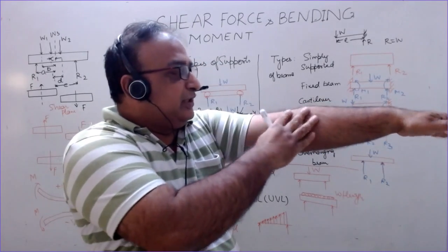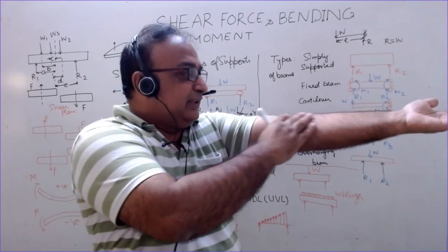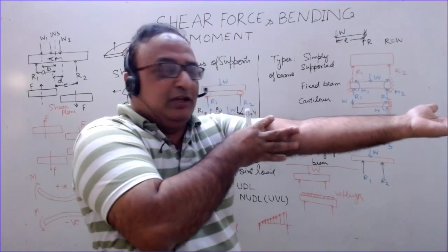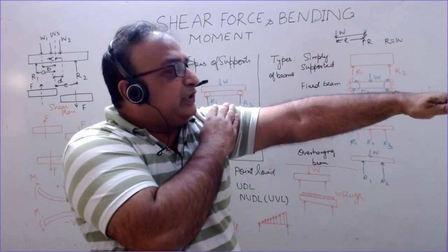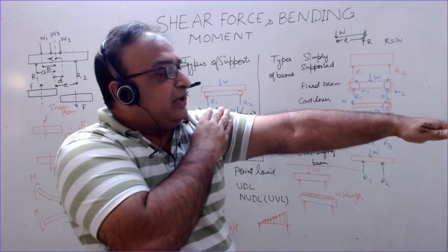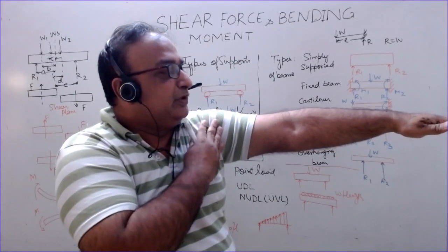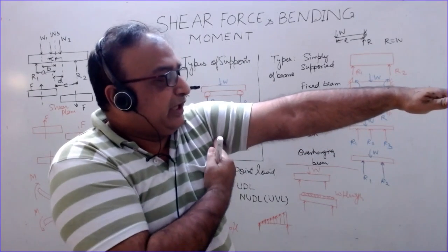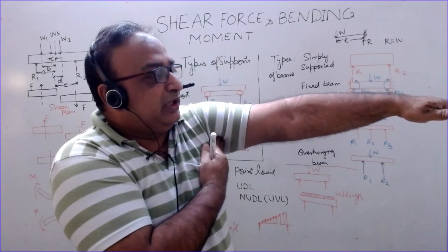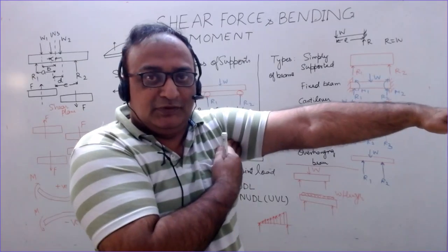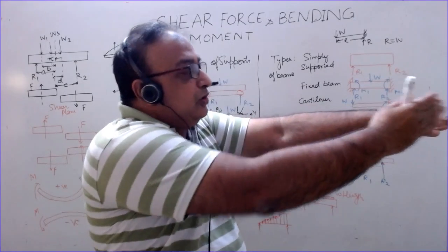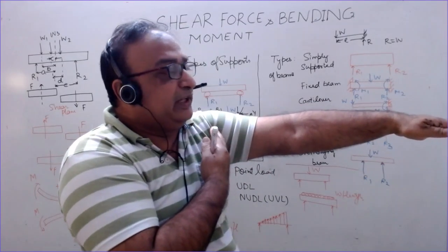If I do not consider this hinge joint, and consider this as a straight beam, okay, this is a hinge joint so we are not considering it. So this is moving the hand in the downward direction. So for the purpose of equilibrium, a load must be acting here in the upward direction so that it can balance this. This is called the fixing reaction. And this load about this point is creating a moment.